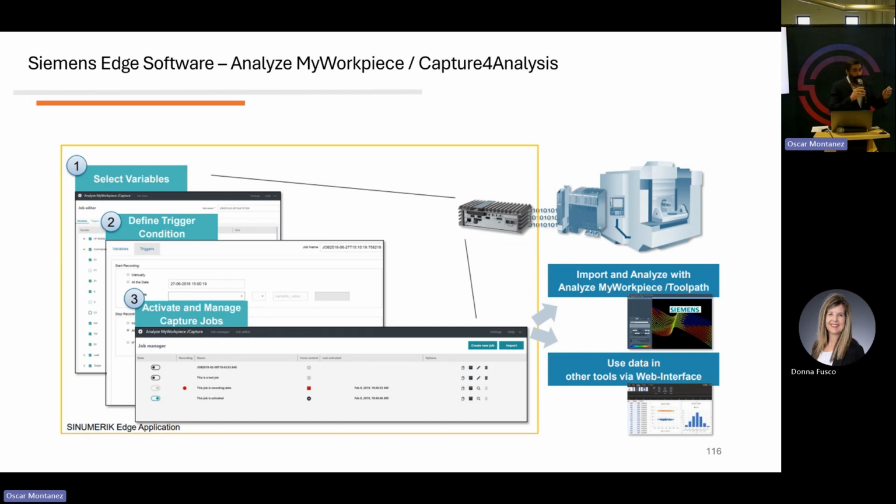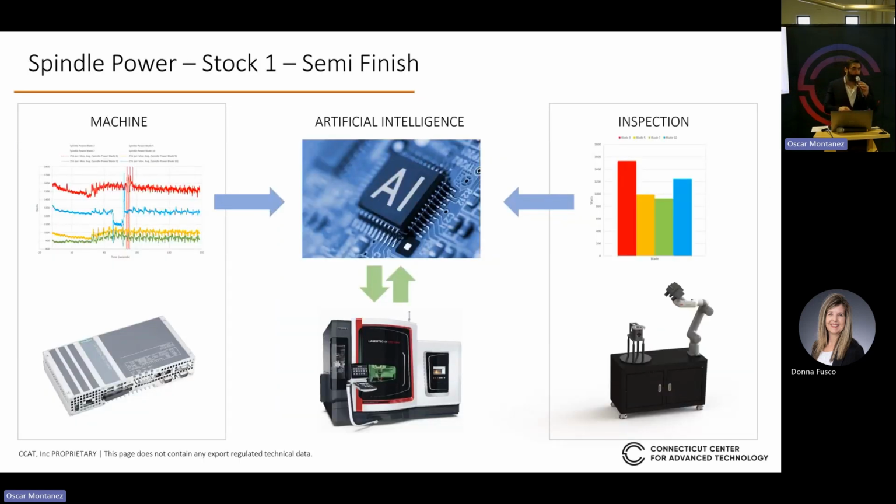So if I have feature ID number 1, which is diameter of a hole, and feature ID number 2, which is depth of a hole, I have one manufacturing operation, op1, that does a drilling operation to produce that hole. I want to capture and segregate the signal just for that hole, because then I want a segregated signal for my next hole. And that's the way I'm able to take the dimension from the feature ID, associate it with a manufacturing operation number, and eventually to my signal. And those are the two data streams that come in to teach a predictive model using AI, machine learning.